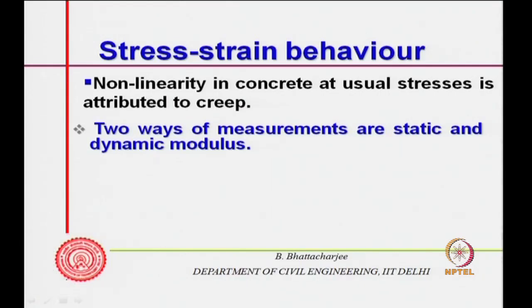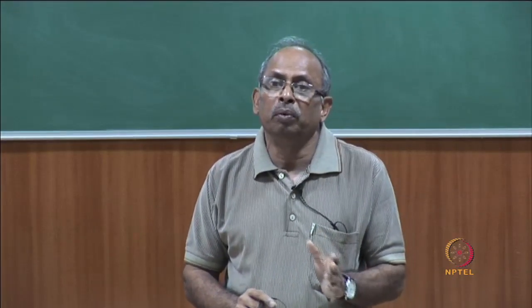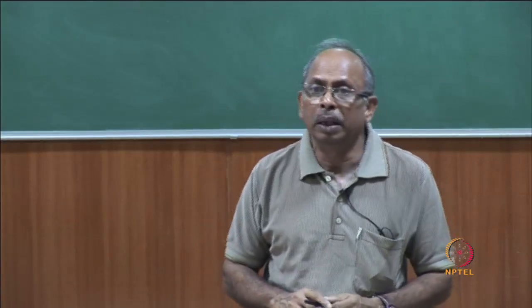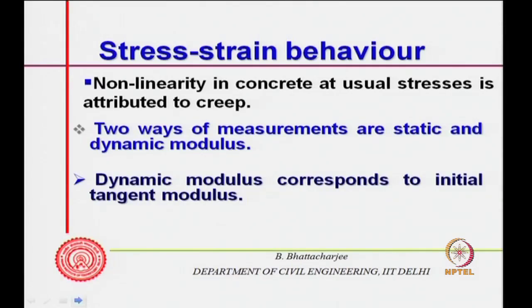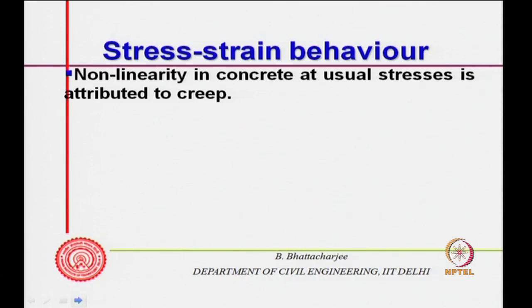So, dynamic modulus is related to wave propagation within the material itself, because the velocity or characteristics of wave propagation is related to the elastic modulus, and one can determine it that way. It is dynamic modulus because there is no load applied as such in a big way, and it corresponds to the initial tangent modulus. So, obviously, this value will be higher than any other modulus, because the behavior is nonlinear.